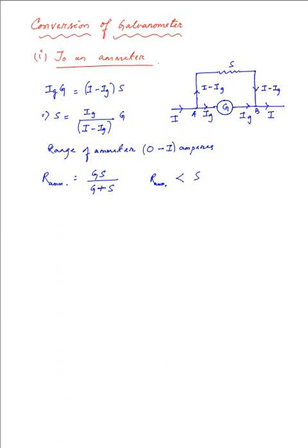Because this is low, this ammeter does not really affect the flow of current, and as a result, this ammeter arrangement is connected in series to the given circuit where the current is to be obtained. It has to be connected in series, of course, because if we connect it in parallel, then it will collect a part of the current from the circuit, and it won't really help.